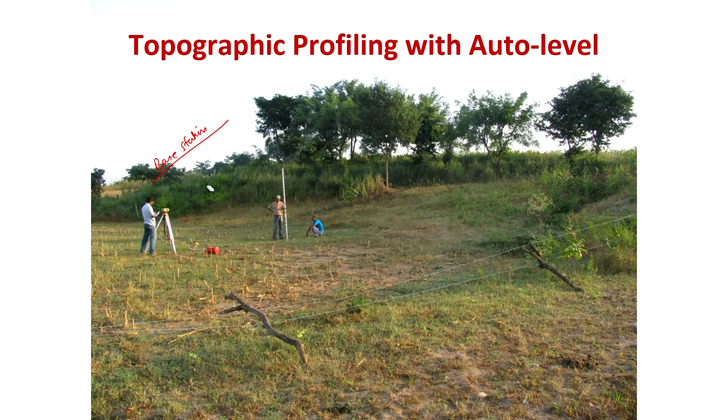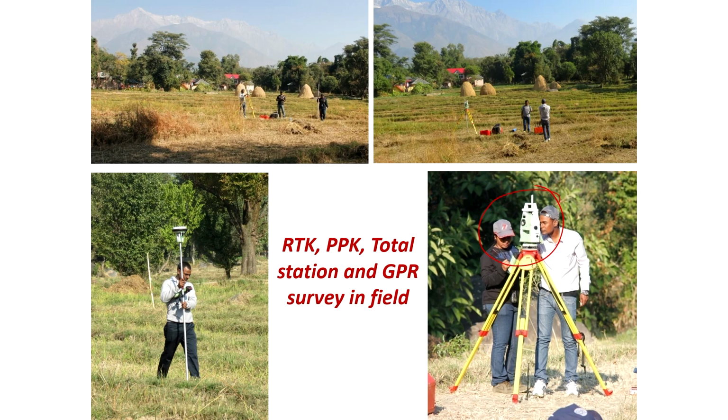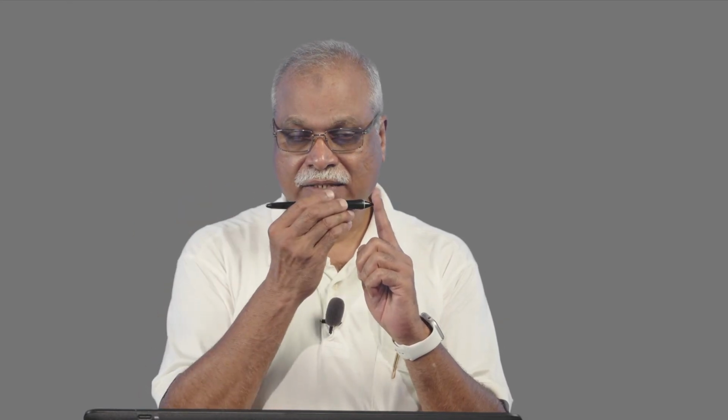Not two people are required, because with the previous one you need at least two persons, one at the station and another moving with the calibrated post. Okay. So, here that problem was resolved. But another point: the total station needs to have connectivity with the prism. So, it needs to have that sort of a line of sight.